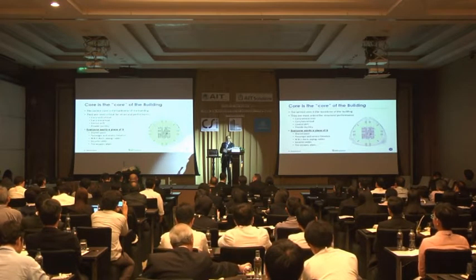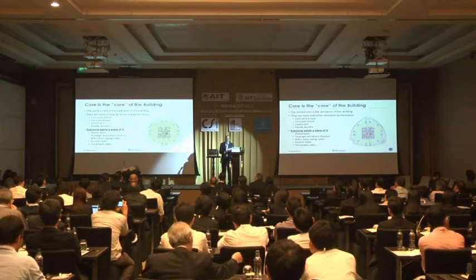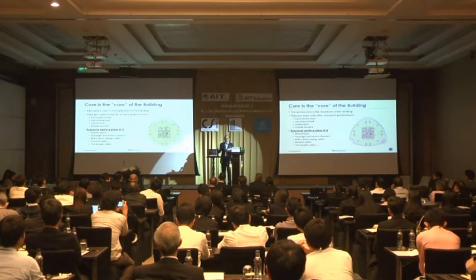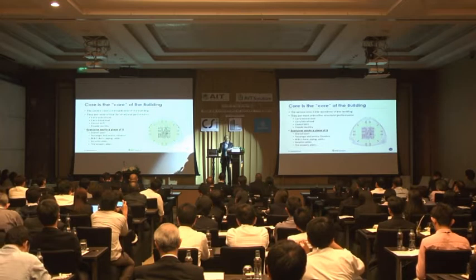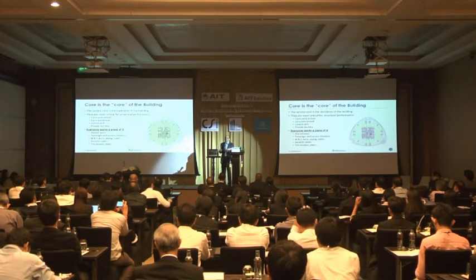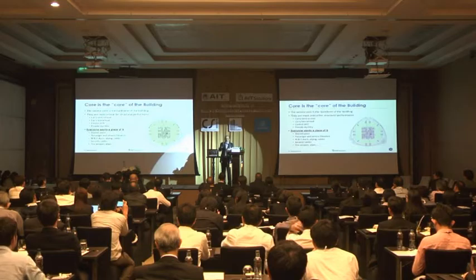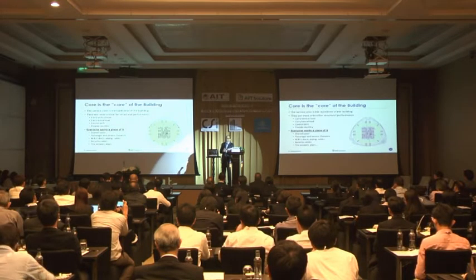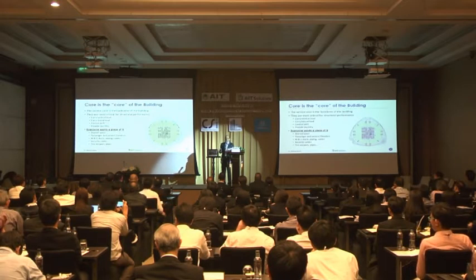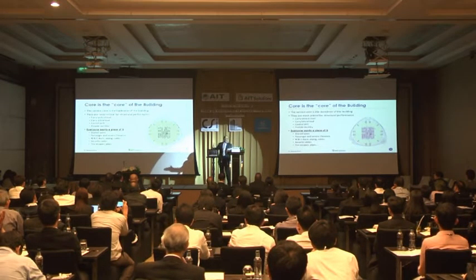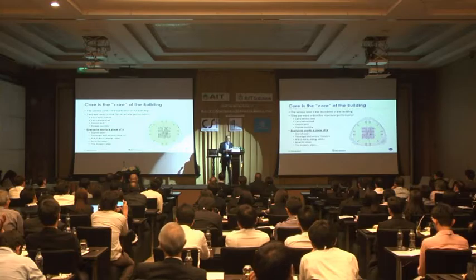we get cries from everybody, because elevators, obviously, they're already designed to fit in there, and there's this set of elevators, not one. So where do you increase the thickness? There is no way to increase the thickness because they have fixed it for their elevator travel. And there are many elevators side by side. So what do you do? You can't change the thickness, and the architect doesn't want to cut into the sellable space.